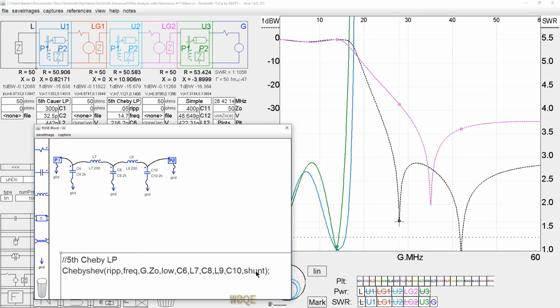And the outside component is a shunt component. You can also build this Chebyshev low pass filter with 3 inductors and 2 capacitors, in which case the two outside inductors then are in series. So this tells us the filter. This is the downside in using this function. The downside is I have to practically design it myself to get it to populate it.